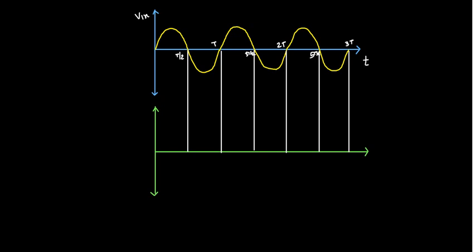This is the time axis, and this is the amplitude axis, the y-axis, showing voltage, and this one we have considered for V output, and this is also time. Our V input is nothing but Vm sine omega t. This is our highest peak Vm, and this is the lowest peak, that is minus Vm. We have considered our diode to be ideal.